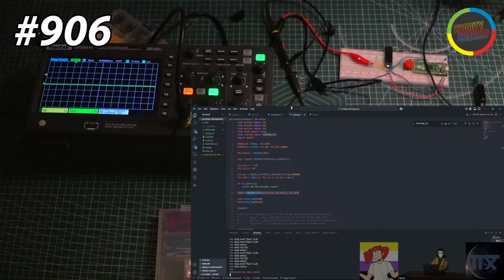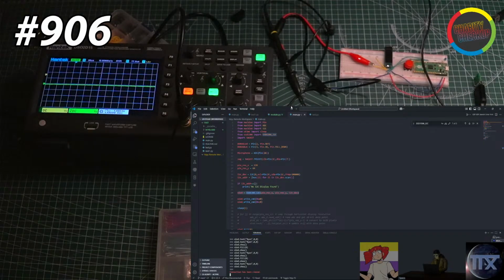Somewhere in the back of my mind I vaguely remember having another USB module. So you almost want resistors too, because I know if you put two resistors on D plus and D minus, I think it's a 5.1 kilo ohm. I'll look at my schematic.